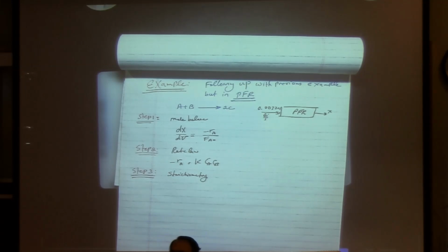Or if your reaction is happening in a fixed-volume batch reactor, it doesn't matter even if the moles change, because the volume is constant, so epsilon equals 0, correct? Sometimes the vessels can have an expandable volume, like a piston and cylinder, and for that one the volume changes.